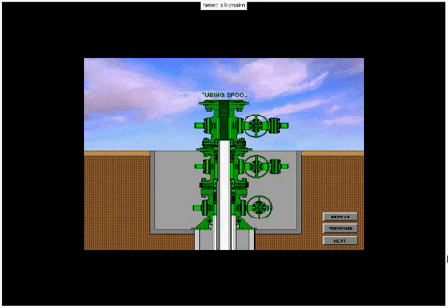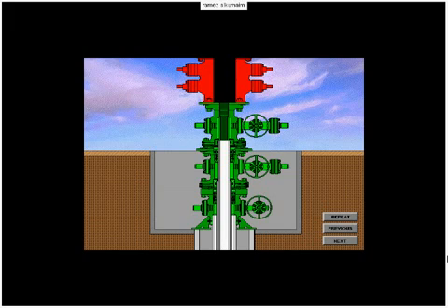The final cut is made to the production casing in preparation for installation of the tubing spool. The tubing spool with a crossover seal is installed in the same manner as the casing spool. After the tubing spool has been installed, the seals and connection are tested, and the BOP system is nippled up. Preparations are now made to run production tubing in the hole. Production tubing is considered any pipe string 4 inches in diameter or less, though sometimes larger sizes of pipe are used.